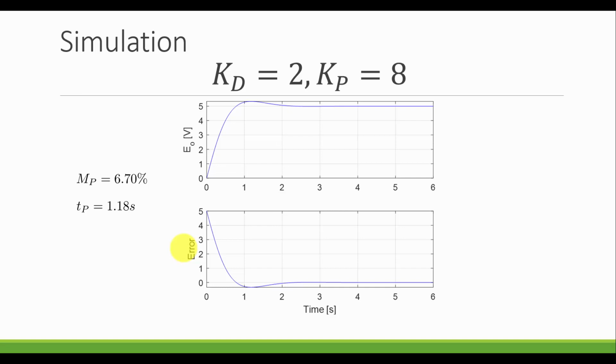But let's compare that to the theory part that we skipped over a little bit here. Why did we choose the poles we did, the -2 plus or minus 2j? Well, in this example, it was just arbitrary, but in the future, we're picking them because of the desired output performance metrics. So let's see what the expected performance metrics would be with this chosen pole.